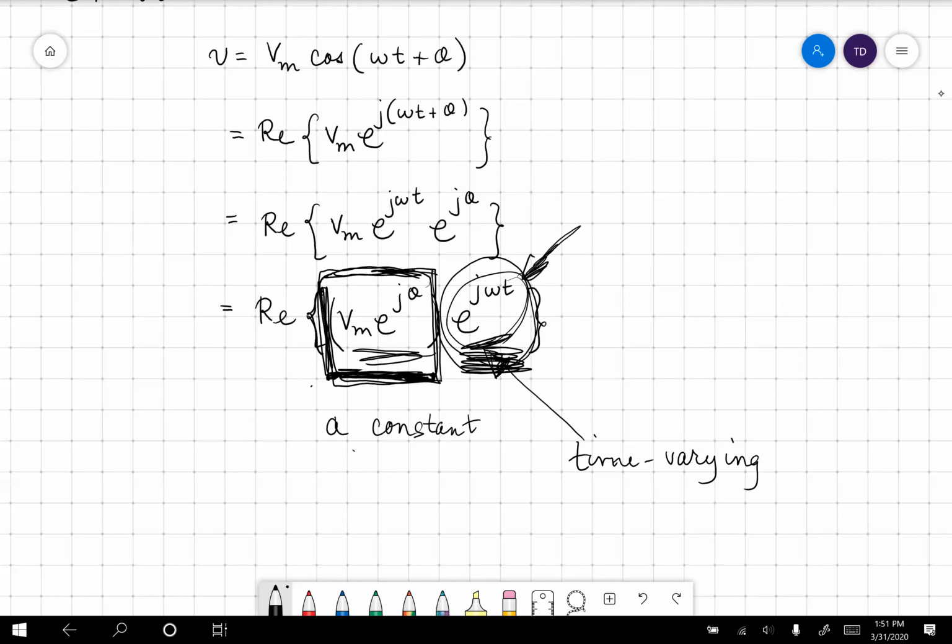We know we're going to get cosines. We have an exponential there. We know we're going to get exponentials. So let's just carry that term right there. And that's what phasors are about. Phasors are about us just carrying that complex term. I know it's complex, but it is a constant. V sub m times e to the j theta.